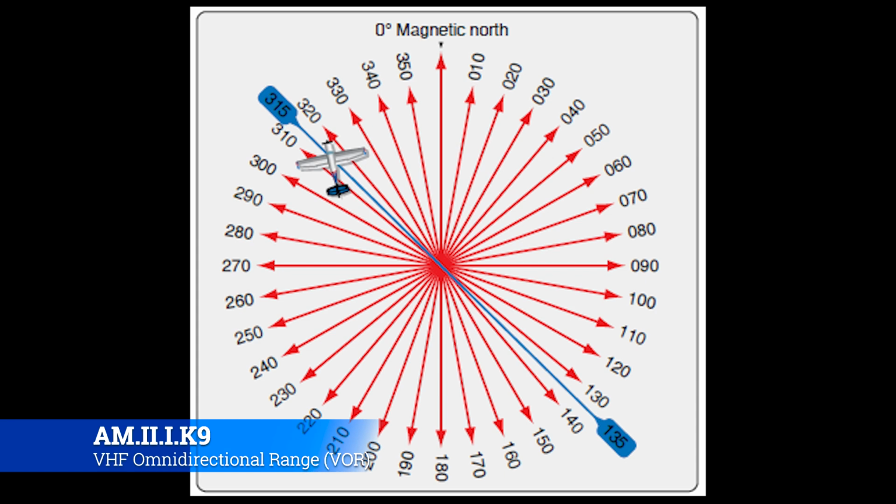That's important because with some VORs you might get the frequencies confused or think that you're tracking one, but you're actually tracking the other one. So it's always good to tune a VOR, then listen to it, hear the dots and dashes, write them down on your knee pad, and then make sure that you're on the right one. That's why that feature of a VOR exists.